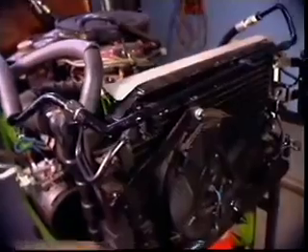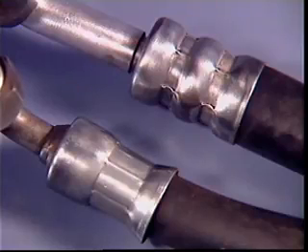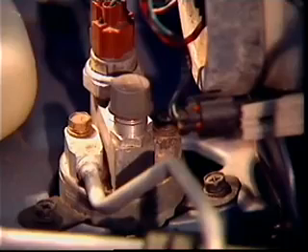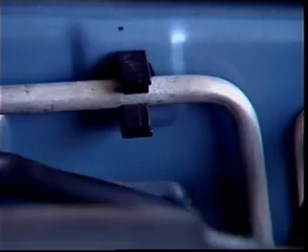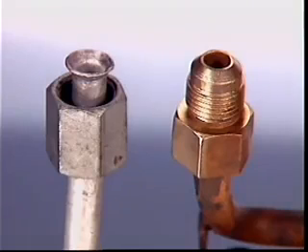Hoses are used to connect the inlet and outlet ports of the compressor to the air conditioning system. The hose connections are crimped to the hose and use special unions that must be carefully assembled to avoid leaks. Pipes are rigid tubes of metal, often found connecting components that are fixed to the body of the vehicle. All pipes must have properly formed bends and must be secured to the vehicle body to prevent fatigue cracks. The connections can be made with flared flanges or threaded unions that are welded to the pipe.